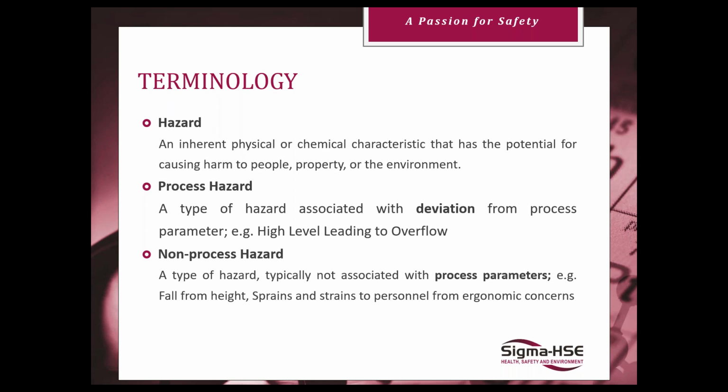Process hazards are, you're operating within an envelope. You have set pressures, set levels, set temperatures. If you were to have a wild swing and you were to lose temperature control on your process, could that lead to an ignition event or a runaway reaction if you've got a reactor and you lose process cooling? These hazards are typical to how you're running your process and not specific to the material as such.